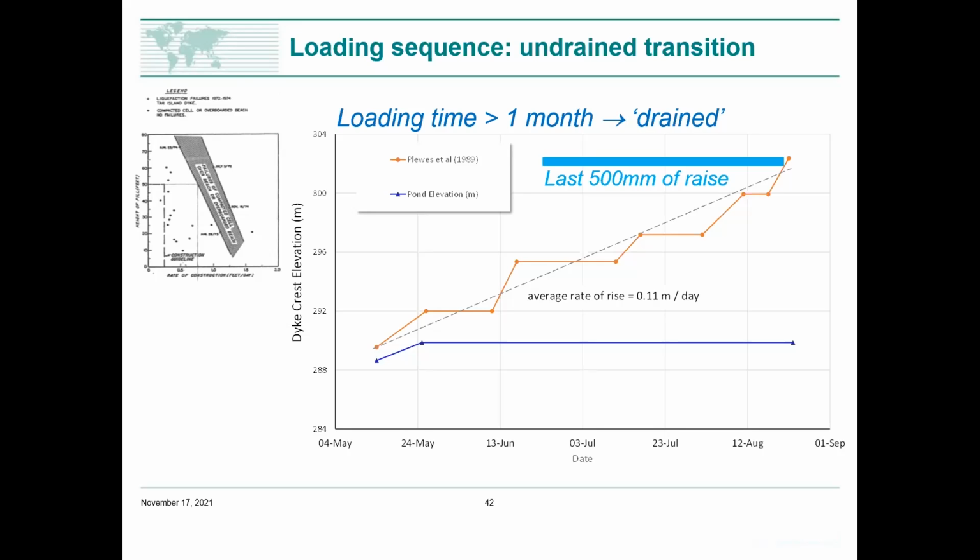And a time factor of 1 is more or less no excess pore pressures, drained loading, and on that basis that calculates out to 1 month. And you can see here we've taken about 3 months. So there's every reason to think that the empirical rules they derived from various test fills actually made reasonable sense, but we didn't run a Biot analysis or a consolidation analysis to substantiate the estimate.